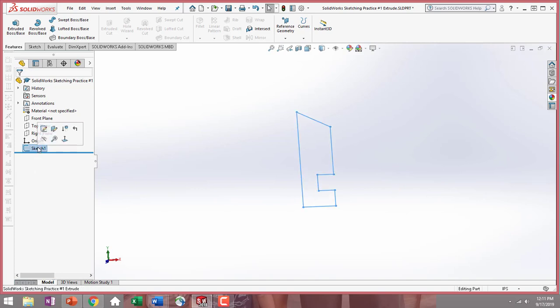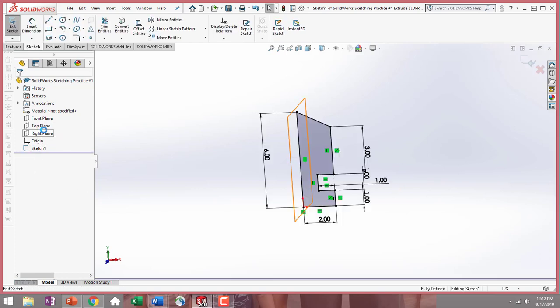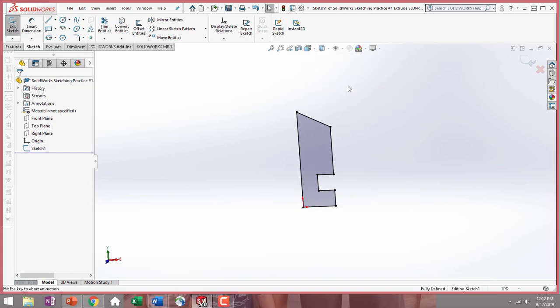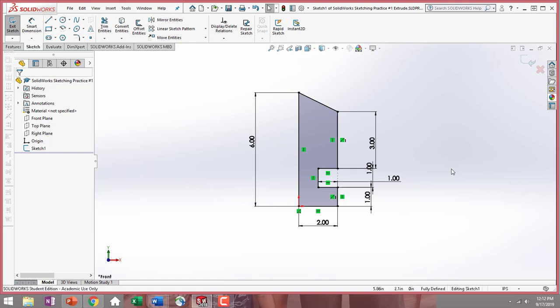I wanted to create this tutorial because we haven't worked with revolves yet. So I'm going to bring that sketch normal to. Now with a revolve, I can create a center line here that my sketch will revolve around, or I can just use this outside edge and revolve it around itself. I cannot pick something that's in the middle of it, so you have to either choose an outside edge or create a new edge to revolve around.